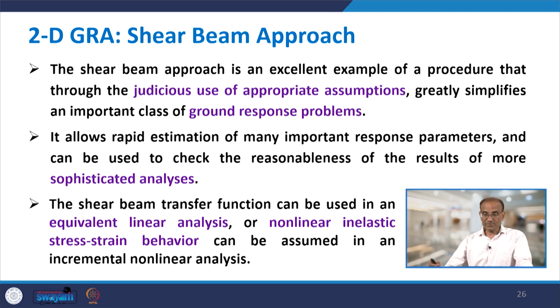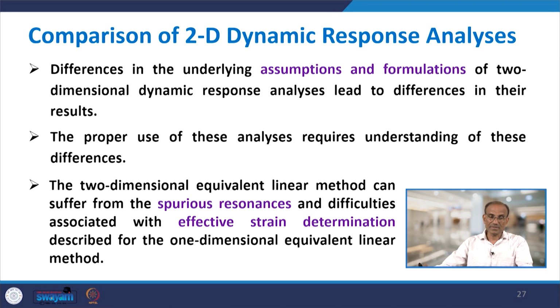The shear beam transfer functions can be used, and equivalent linear analysis or nonlinear inelastic stress behavior can be assumed in an incremental nonlinear analysis. So while using the shear beam you may have equivalent linear and you can also have nonlinear. Continue with 2D ground response.